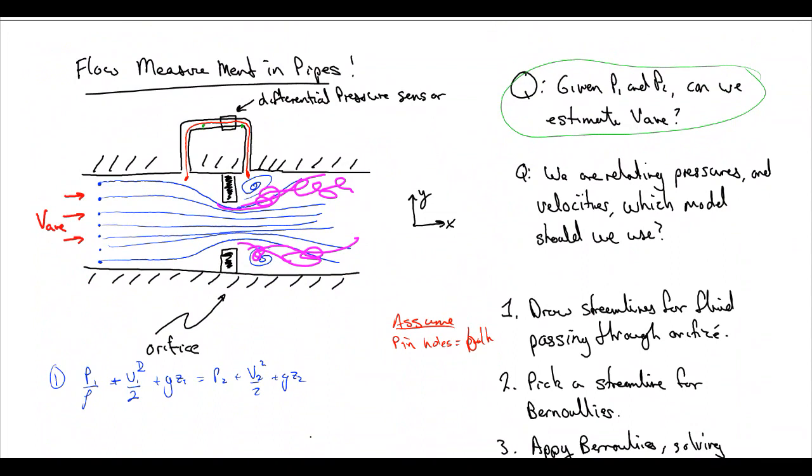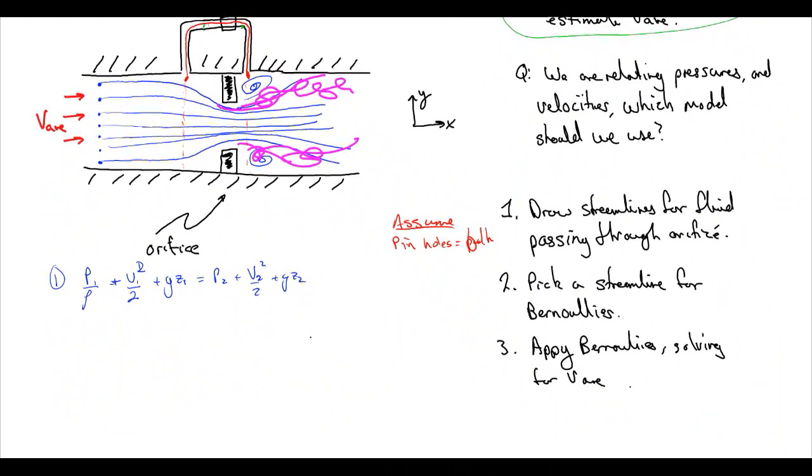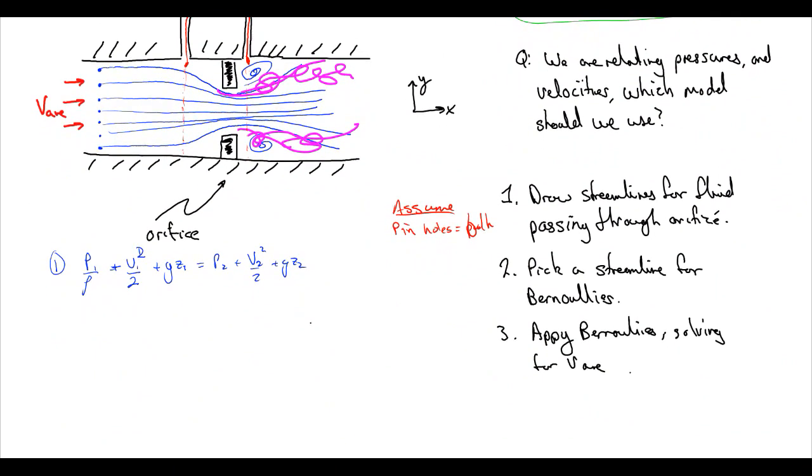And the reason we can assume that is if there was a pressure gradient in this direction, again, there would be fluid motion in the direction of the pressure gradient. There has to be some acceleration of the fluid. So either the fluid has to be going around a corner or something like that. And since there's not, we can assume that the pressure is pretty much equal across this whole entire cross section. And the same is true here. We have some kind of average pressure that exists here. So P is equal across the entire cross section.